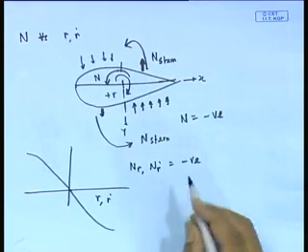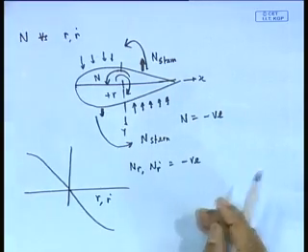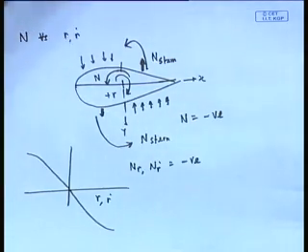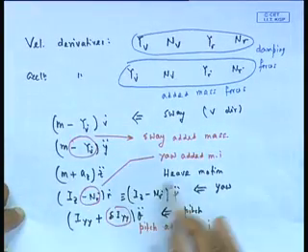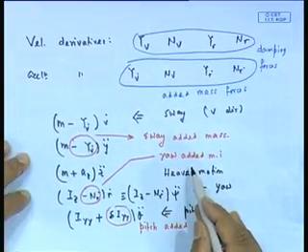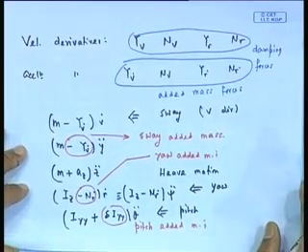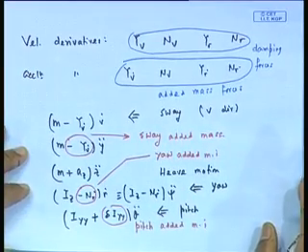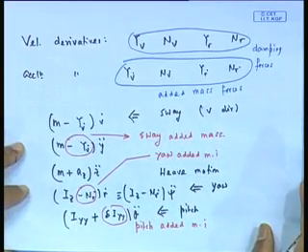in fact N r dot, we have seen earlier, I just explained here, minus N r dot is yaw added moment of inertia, just like pitch added moment of inertia. In fact, it will have a magnitude of almost mass into radius of gyration square, which is something like 0.25 L, a very large negative number.